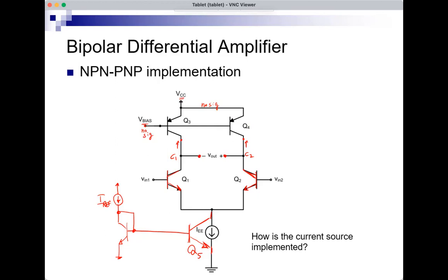So maybe we should consult the formula sheet for resistances. If we do that, we get the formula for the resistance seen looking into the collector of a BJT, whether NPN or PNP. When there's no signal at the base and no signal at the emitter, we see small RO. That's similar to the MOSFET when we look into the drain with no signal at gate or source.